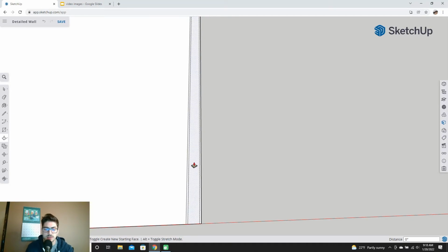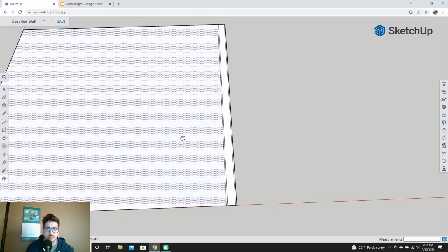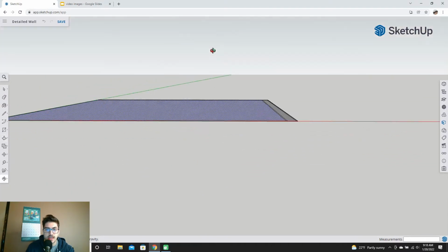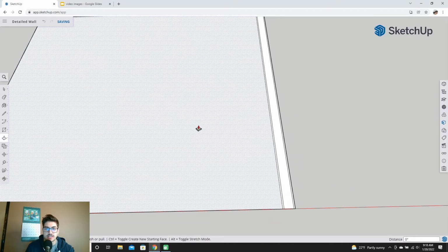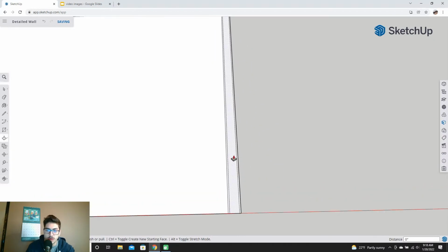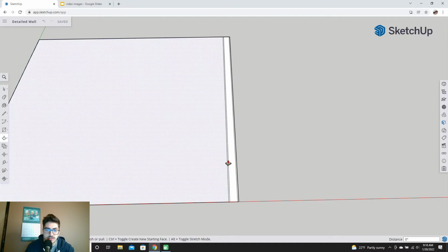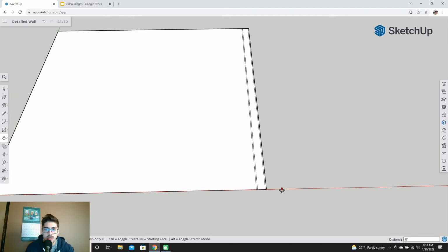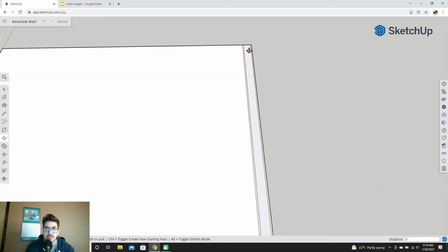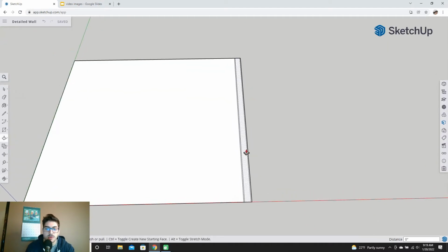So the first thing I'm going to do is grab my extrude tool, the little arrow pulling out of a rectangle, because right now we just have this flat sheet of our 10 by 10 room and then one of the walls. And another thing to keep in mind, if your room is 10 by 10 and you want to model all 4 walls, you actually are probably going to want to extend these past the edges, but we're just going to do one wall for now.